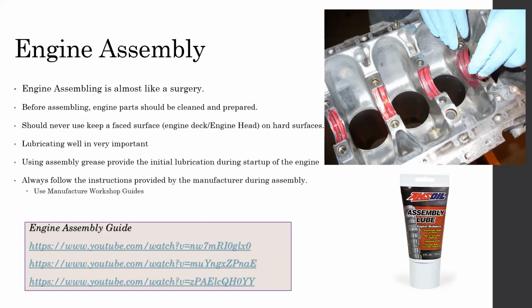Assembling an engine is a very important process, and it's more or less like a surgery, because even in a surgery you have to wear gloves and you can't take any debris inside. Similarly for engine work, you have to be very clean around the engine. You have to make sure that nothing goes inside the engine unless it actually belongs inside. So wearing clean gloves and keeping everything clean is very important.